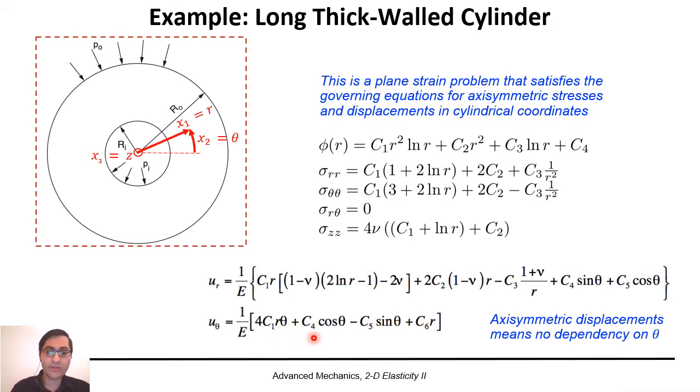We have C1, C4, C5 here, and we have C4 and C5 here. Anyway, we had only C4 in the equation for phi, and we didn't have C4, C5, or C6 in the equations for the cylindrical stresses. But at least it helps us to cancel C1 completely. So as a result, our equations are now even simpler.